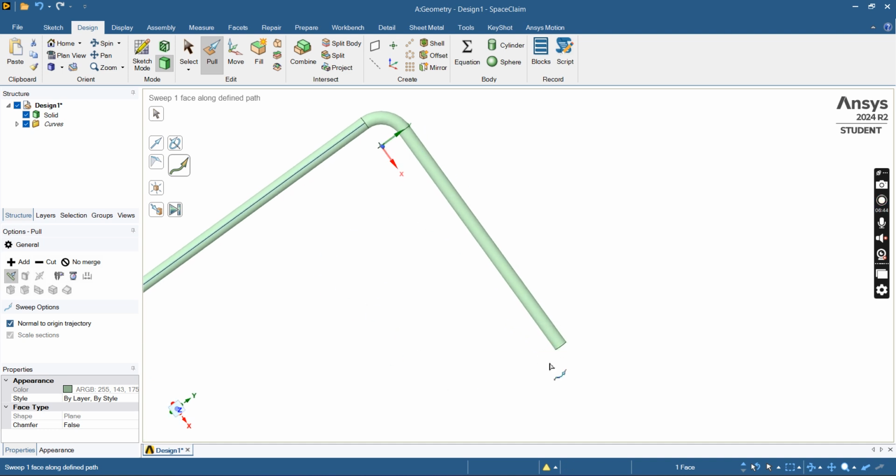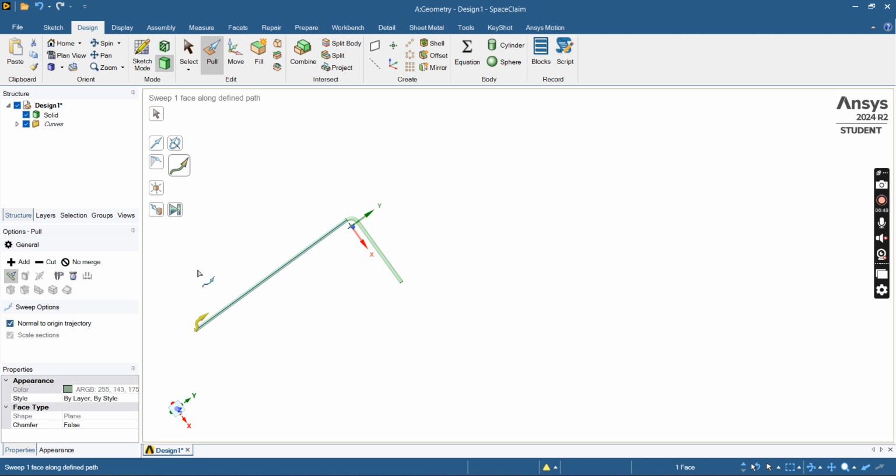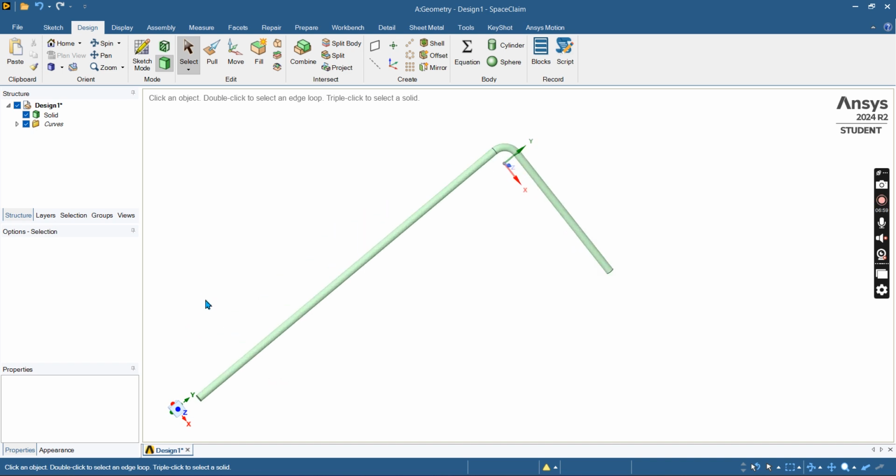So I have a shorter length of the arm in the X direction and a longer length of the arm in the Y direction. Now escape, again escape, again escape. So now our geometry creation part has been done. Now we have to name all of these surfaces. As you have known from our previous experiment of flow through a laminar pipe, we have to name our surfaces. So similar work has to be done in here as well.